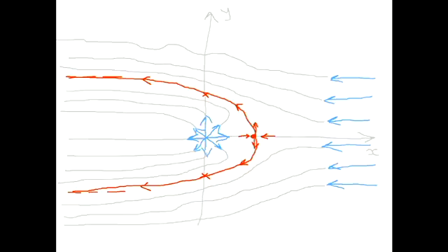So actually, there's only one way that you can sketch this flow if you follow those rules. Maybe it's not very believable because we'd already seen the flow before we sketched it, but you should try it in your tutorials. Once you've found the stagnation points, usually you can have a fairly good stab at sketching that flow. There's only really one way that you can sketch it, as long as you remember those simple rules and you locate those stagnation points correctly.